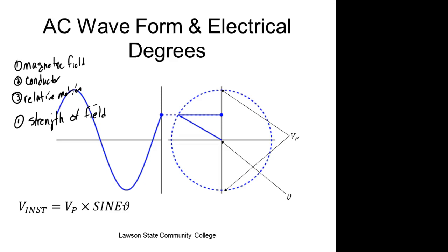One people won't say is the wire gauge. Wire gauge has nothing to do with the amount. What it determines is how much current you can get out of the thing, because that's determining the internal resistance, right? You can use bigger gauge wire, but you're not going to get any more voltage because it has nothing to do with the gauge of the wire. What it depends on is the number of loops.